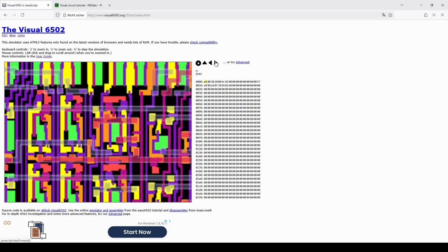If we step the simulator a bit, we'll quickly see that this line here constantly pulses on and off every time I click this. This simulator actually simulates every half cycle, which makes it pretty easy to see this. So it will probably not surprise you to learn that this is actually the clock controlled pin. This silicon is apparently called C clock. I'm not sure what the C stands for, but whatever, it's Phi2 is what it is. So these are the inputs.